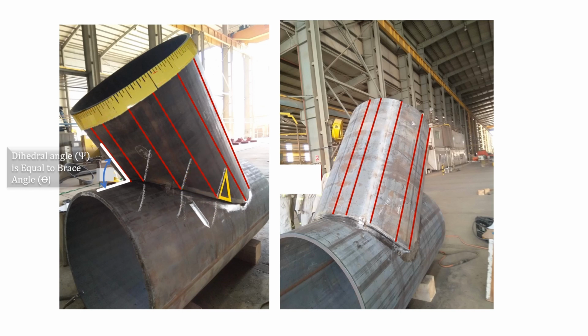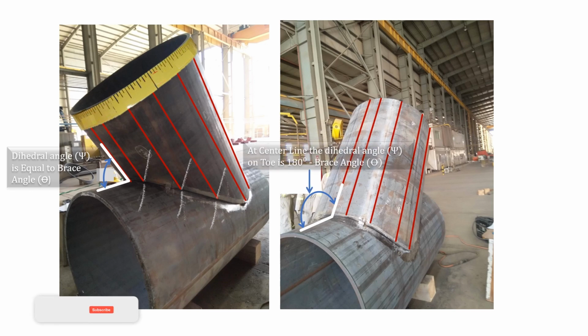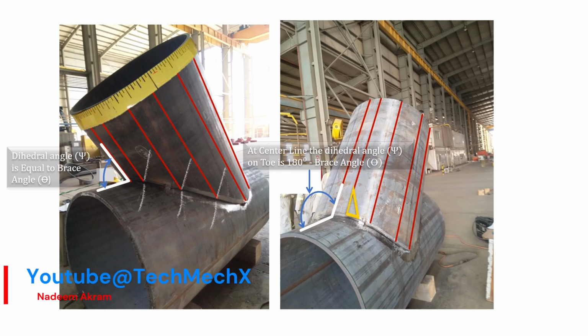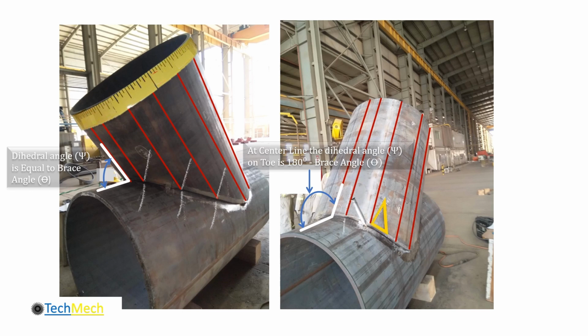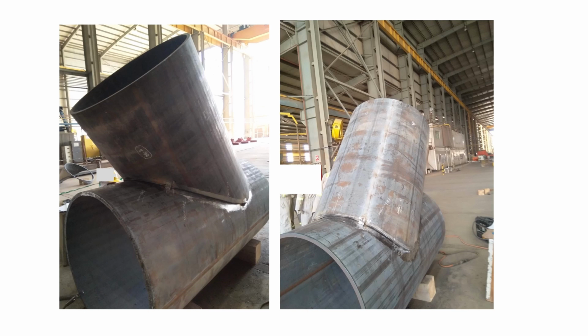At the center on the toe area, the dihedral angle will be 180 minus the brace angle. Here the assumed brace angle is 30 degrees, so the dihedral angle at the toe will be 150, which falls under zone 1. Continue marking perpendicular to the line of the weld. Before continuing further, just observe how the drawn perpendicular lines keep changing along the line of the weld. Let's zoom in to have a closer look at the different areas of the tubular connection.